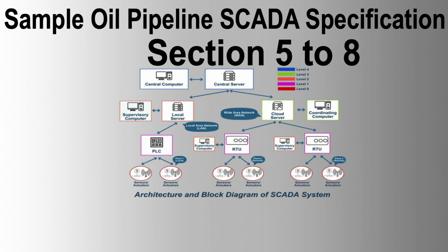Section 8. Pipeline Applications. 8.1 Configuration. The Operating Standby Pipeline Application Software (PAS) platform configuration shall form part of the MCC and SMCC control centers. PAS packages shall reside in their dedicated server computers and link via high-speed Ethernet LAN using TCP/IP protocol. The model shall receive specific quantified data from the SCADA database in a continuous stream. The entire measurement system shall be scanned at a rate specified by the SCADA seller for optimum model performance, determined during the leak sensitivity study. Results of all calculations shall be transferred back to the SCADA system databases.